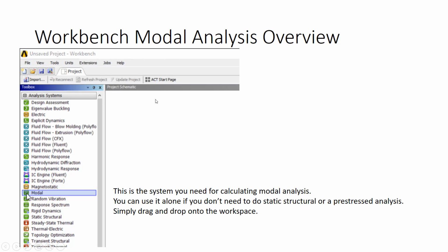So in Workbench, there's a modal analysis solution, as you can see over here on the left. You're going to select that modal to run a modal analysis, and you can drag that into the Workbench and use it directly as is if you don't want to do pre-stressing.